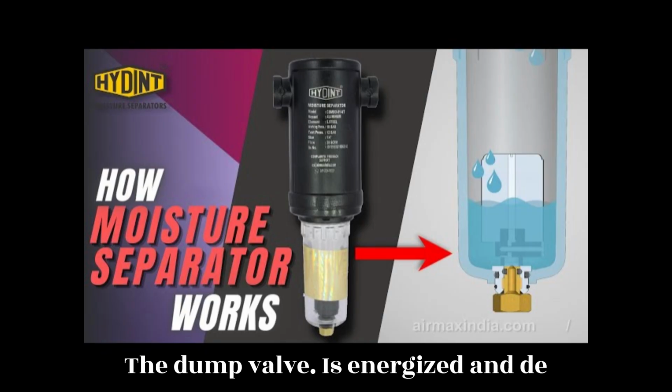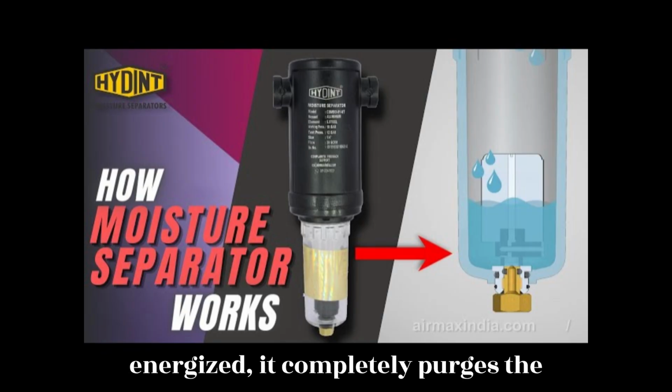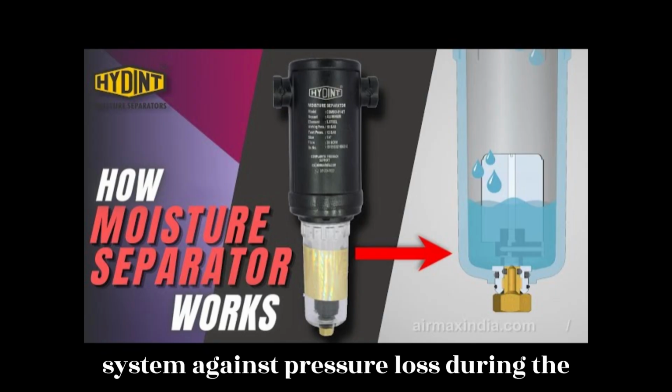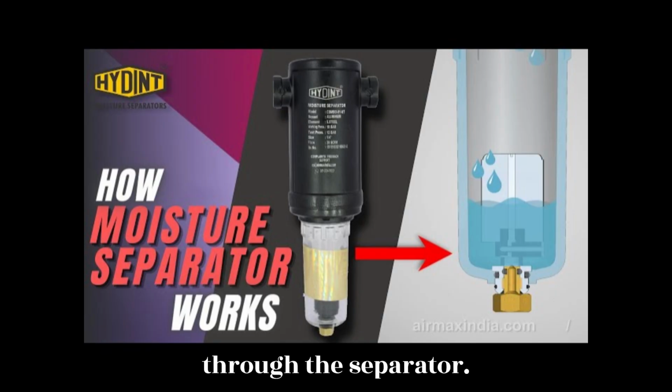The dump valve is energized and de-energized by the pressure switch. When de-energized, it completely purges the separator reservoir and lines up to the compressor. The check valve protects the system against pressure loss during the dumping cycle and prevents reverse flow through the separator.